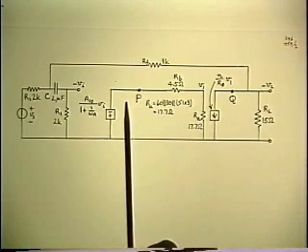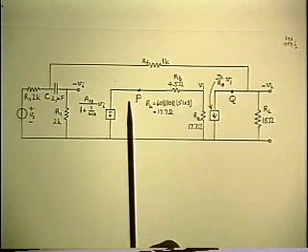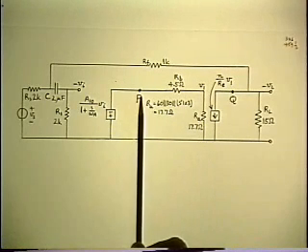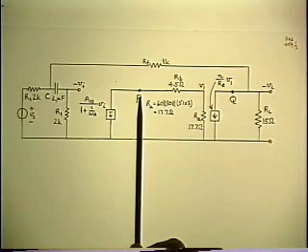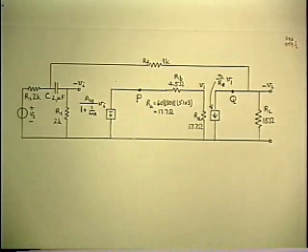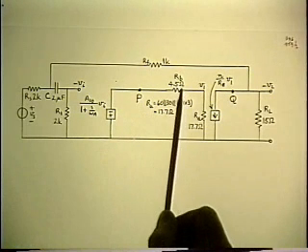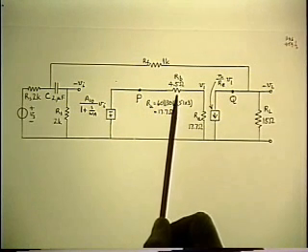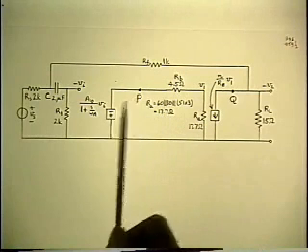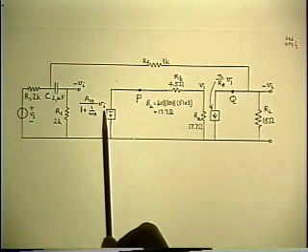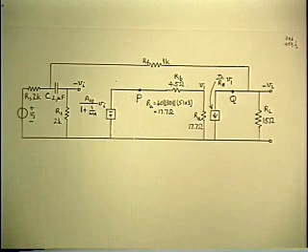But let's go back and look at what would happen if we did do voltage injection at point P. We could do it analytically, but we couldn't do it on the bench, because point P doesn't exist physically. Because the RB, 4.5 ohms, actually represents the output impedance of that driver amplifier. So you can't get at this point.